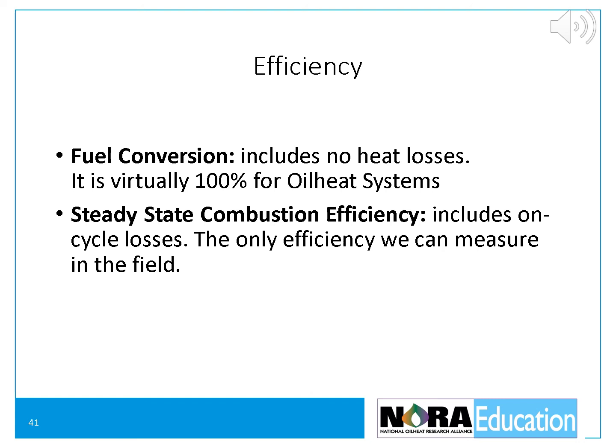Combustion efficiency or steady state efficiency includes the fuel conversion efficiency, the amount of excess air used, and the efficiency of the heat exchanger. This is the test technicians do in the field. Combustion efficiency only describes on-cycle losses. It does not include jacket losses, off-cycle losses, distribution, or outdoor air infiltration losses. So combustion efficiency is a great service tool, but it's not a very good sales tool, and it should not be the end of the analysis.